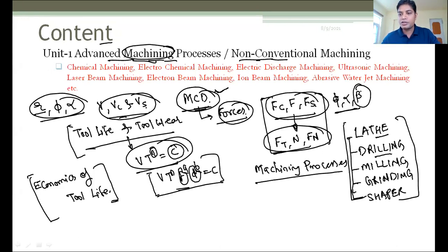In milling operations, there are different types of milling machines, like the horizontal milling machine, vertical milling machine, universal, simplex bed type, duplex bed type, triplex bed type. That also we have studied. And on the basis of what cutter we are using, simply we can say like a grinding wheel, a kind of wheel on whose periphery there are teeth, which will remove the material. Fine. And end mill cutters are also there, which are mounted perpendicularly. So that we have studied.